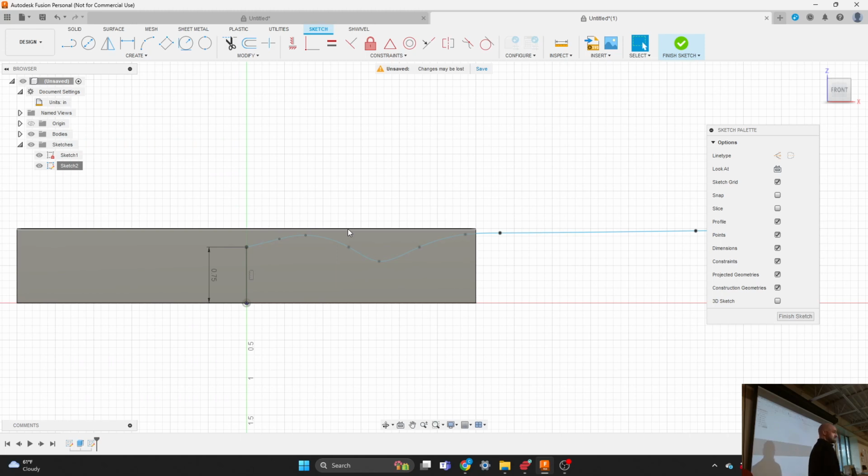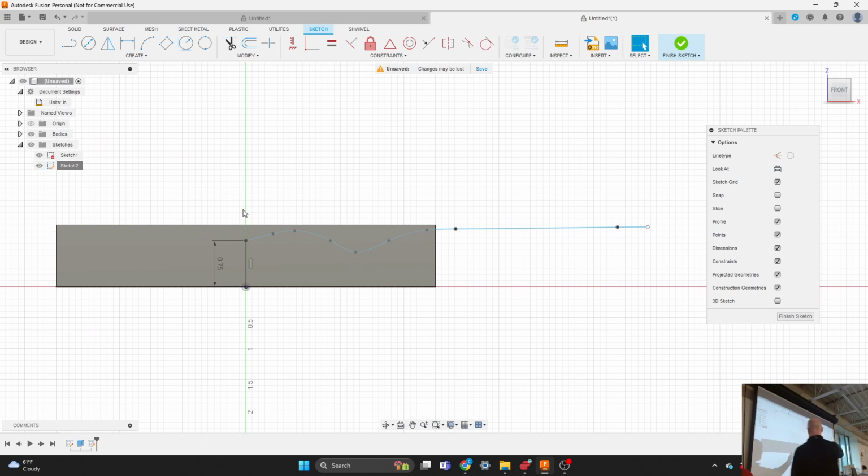You can make splines tangent to things, define distances between points on a spline, and give it distances in X and Y. It's possible to fully constrain a spline. But I would argue it's pointless to fully constrain a spline, because the point of a spline is to have a curved, morphing shape. So, as much as I like making fully constrained sketches, this isn't going to be one.